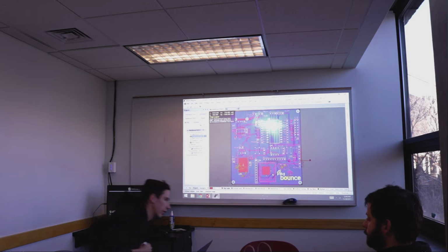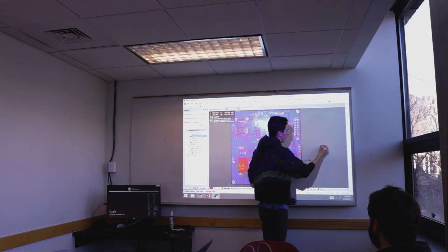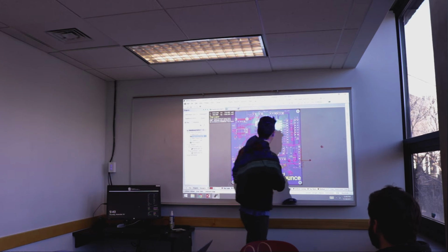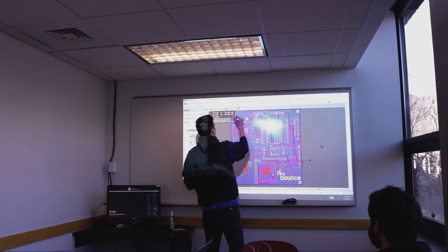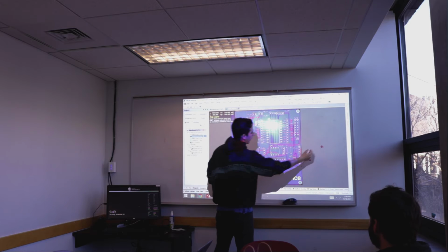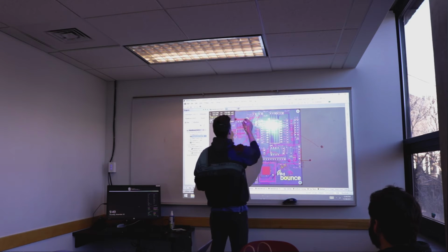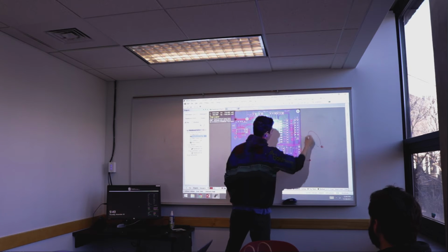Essentially the signal, when it's getting to the via, say this is a via, it needs to come all the way back up to here. Instead of just going straight with the ground plane, it's doing this weird go around everywhere, go back.